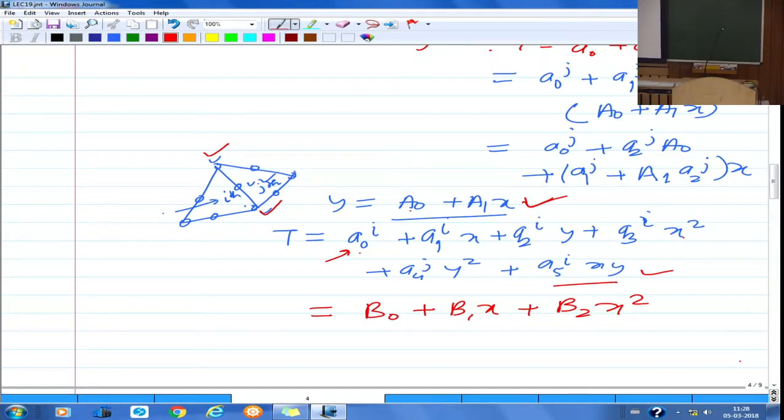So already through the assembly process we enforce that the temperature value is the same for the nodes belonging to both the elements. So at 3 locations we are forcing that T is the same for both the elements.